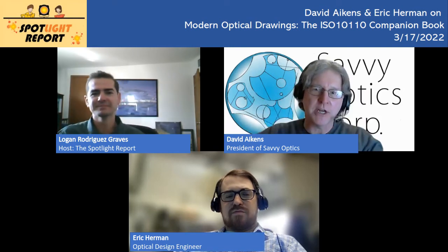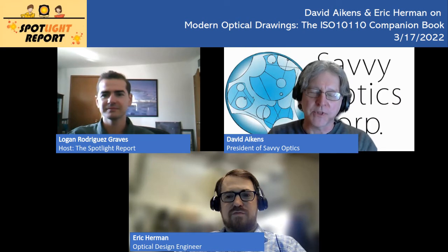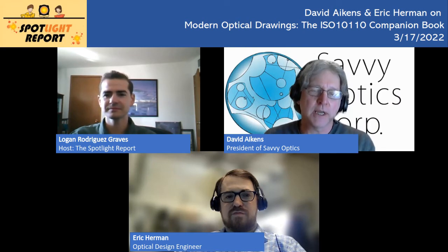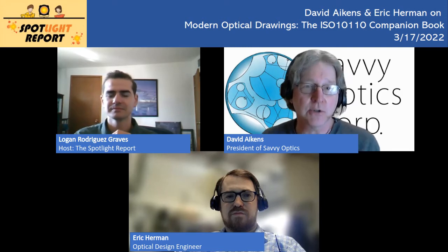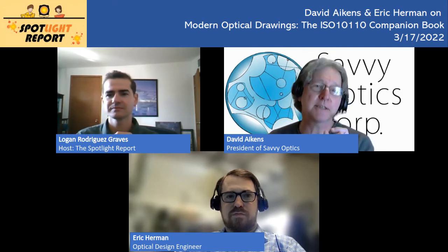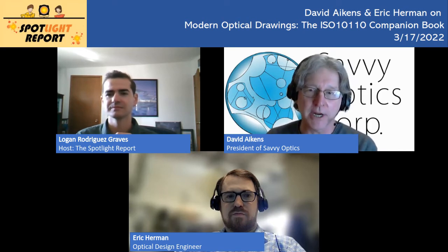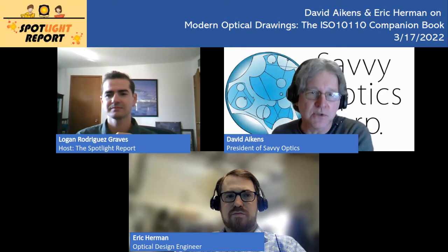The spherical aberration shape has kind of a fourth-order function to it. So that's form errors. And texture, well, roughness is easier to describe. Roughness is micro roughness. It's stuff going on at a very fine scale, like microns, not the whole part. And then waviness is the stuff in between.